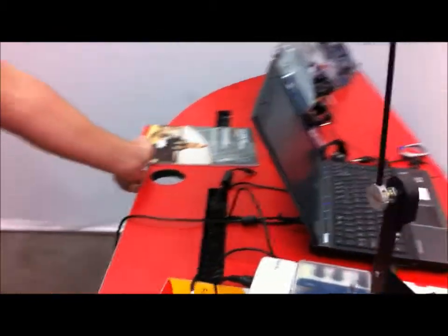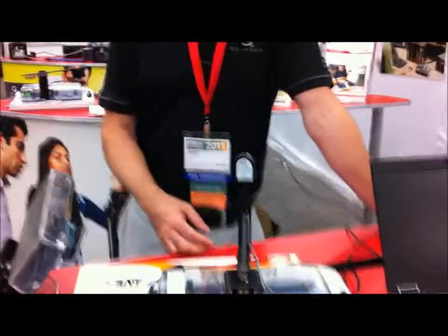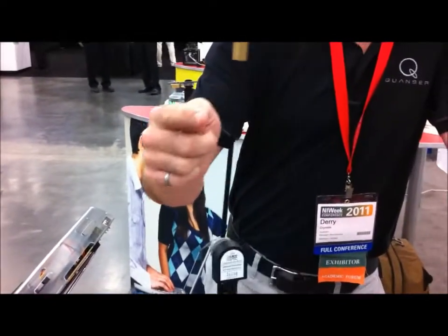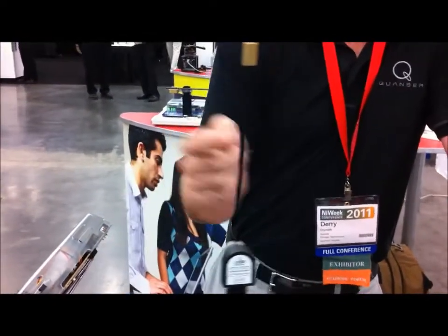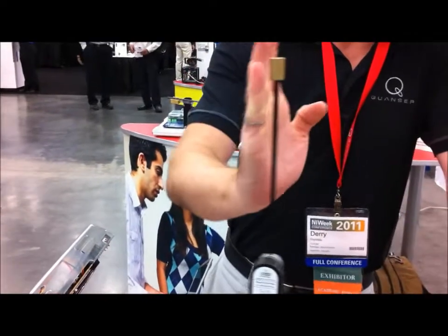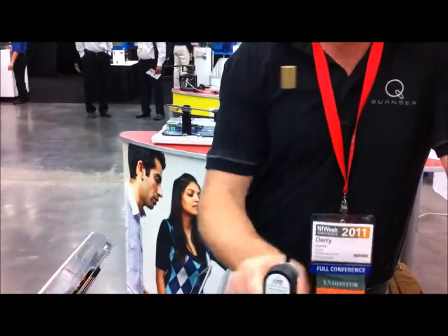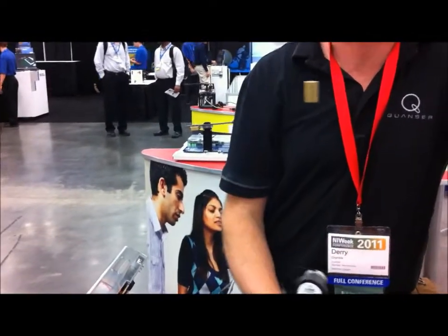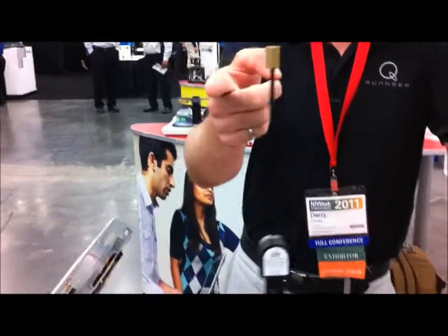So in this case here, we got a nice demo of the inverted pendulum. It's a classic controls problem. And what we have is a DC motor acting on a little link here, and the position of this pendulum is being measured by an optical encoder. So as the optical encoder measures this thing falling off, the motor at the bottom moves in that direction based on some state space control laws to try to catch it.